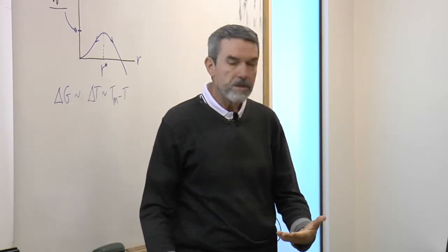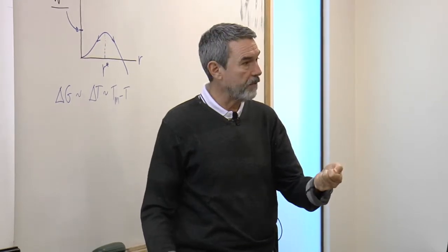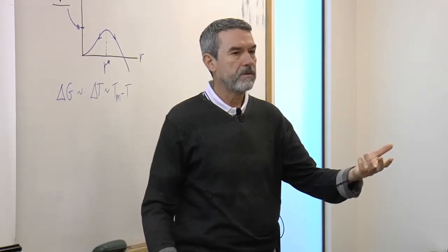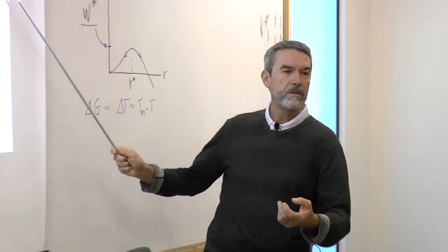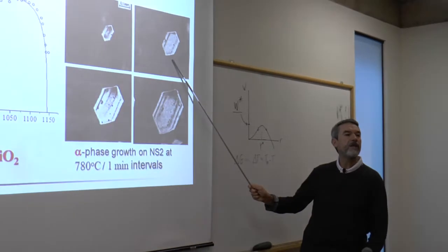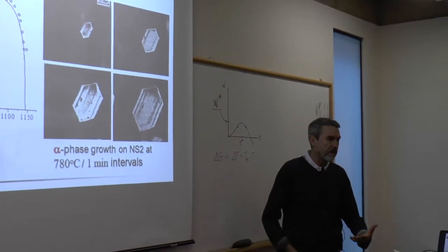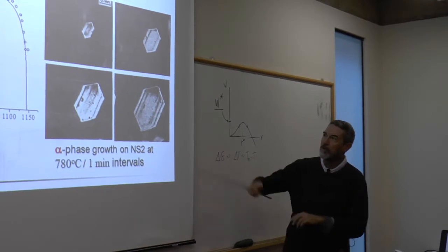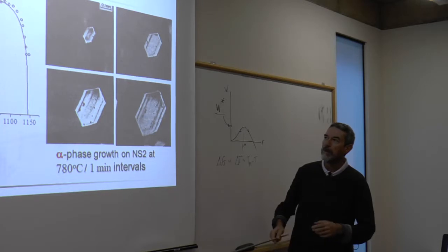Then you look at the crystal at room temperature. Then you can reheat that same sample for another hour or so. That crystal will grow, and then you quench it again, bring it to the microscope and measure the size, and so on and so on, so you can follow the size evolution of a particular crystal.